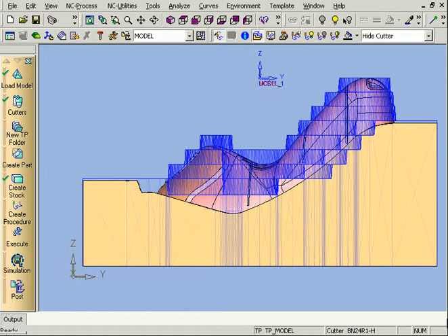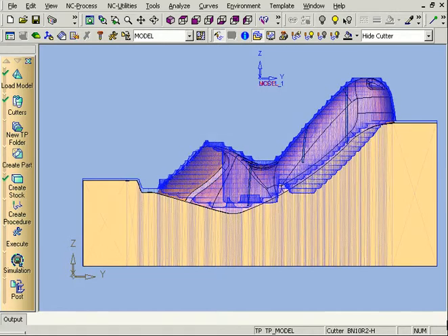It calculates efficient and safe tool paths based on the knowledge of the actual remaining stock to be used for these options. Optimized machining strategies, efficient air connections and plunges, adaptive approach and retract types, and constant chip load control. At all times, re-rough avoids collision of the tool and holder.